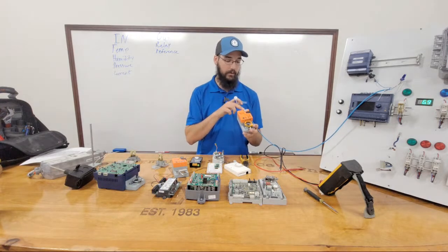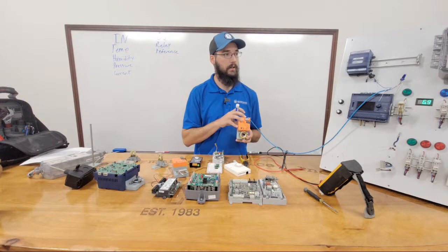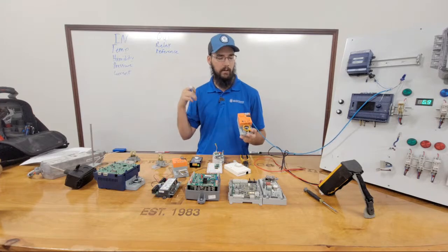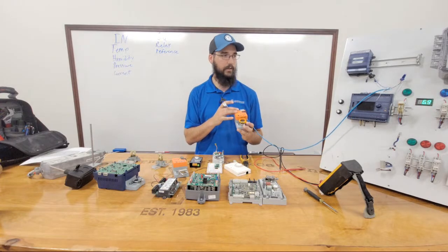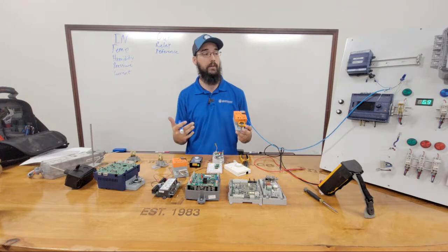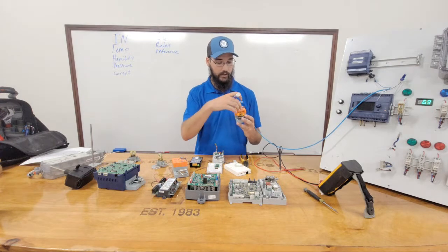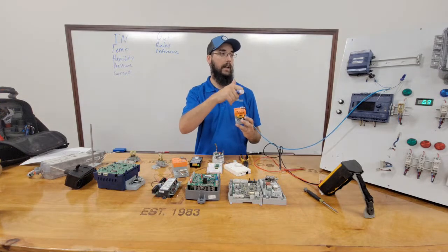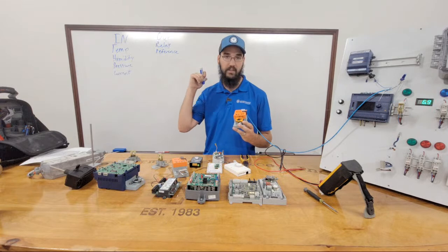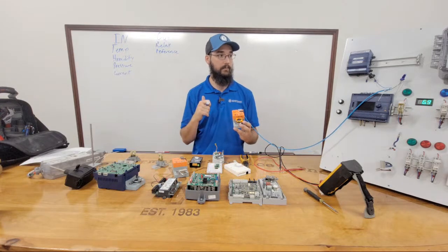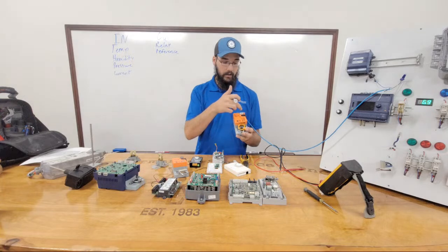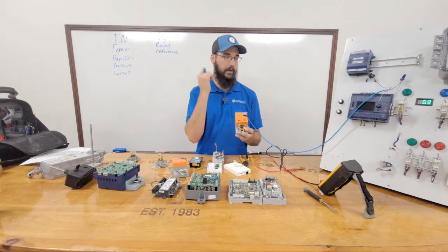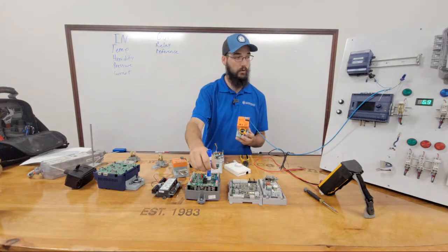At the same time, there's a fourth terminal up here. That is a reference signal coming out. And I'm pretty confident if you look up the literature on this, it's actually going to refer to that as a reference. That reference is actually a potentiometer of some sort inside of here that is sending a position signal back to the automation. So at that point, your first 3 terminals become output terminals, or really terminal 3 is your output signal coming from the controller.